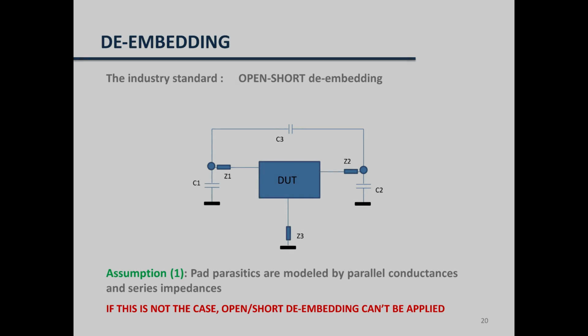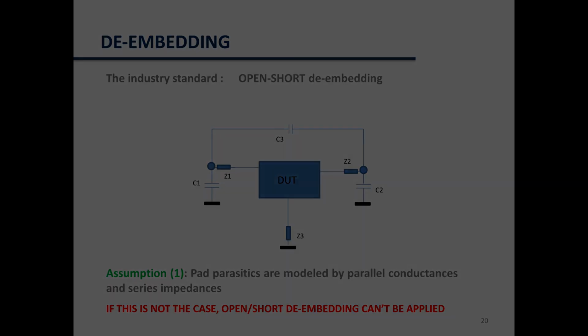Regarding de-embedding, the industry standard is the open-short de-embedding. In order to apply such de-embedding, you need an open and a short dummy structure. The assumption to realize this de-embedding is that pad parasitics are modeled by parallel conductances and series impedances only. If this is not the case, open-short de-embedding cannot be applied.